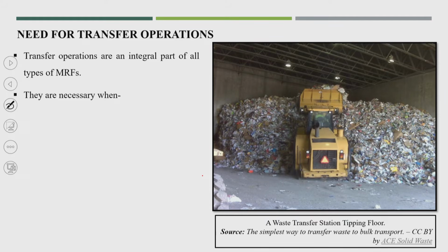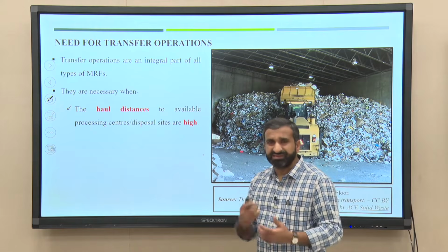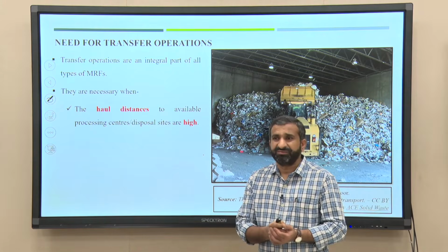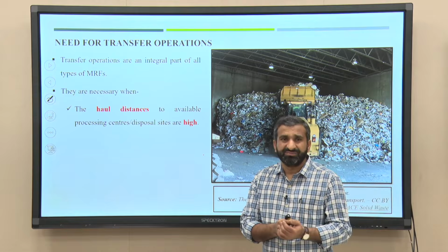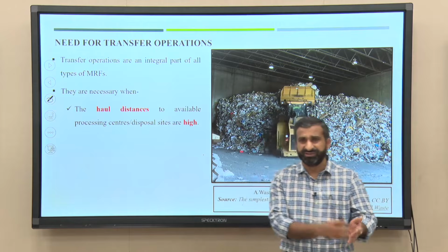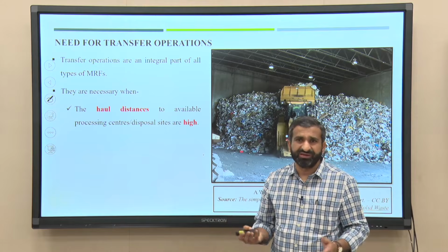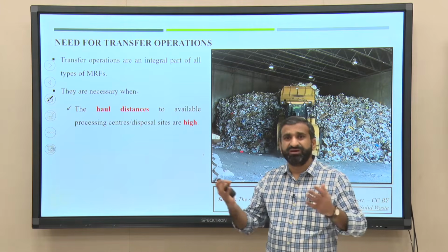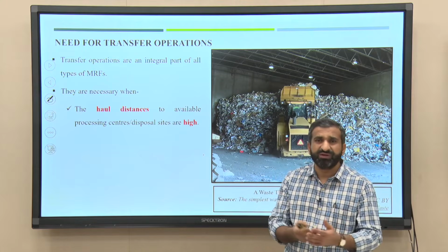Transfer stations are necessary when the haul distance to the available processing center or disposal sites is high. If the haul distance is high, you can ask, sir, what does high mean? It depends on the city. 10 kilometers, 20 kilometers, even 25 kilometers of traveling in a city is possible, and if you have proper roads where these larger vehicles can travel, it will be economical.